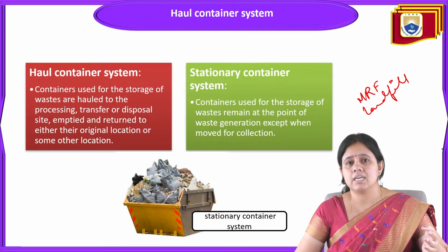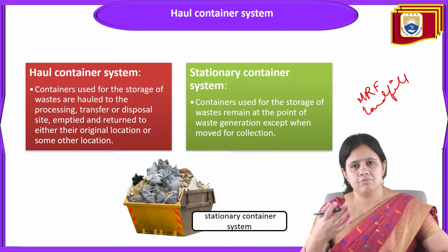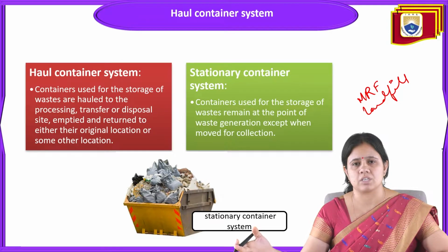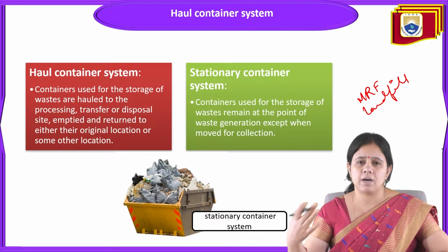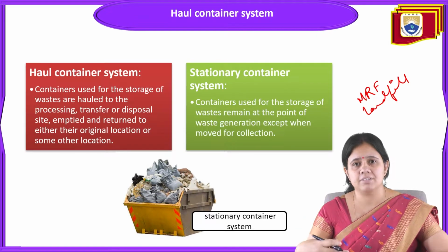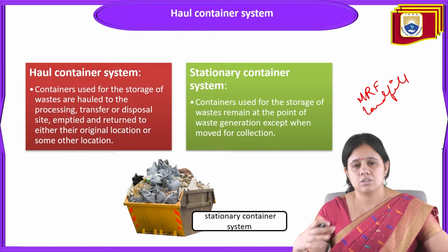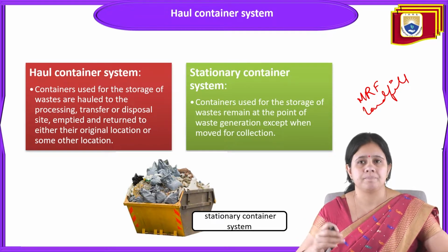But in the stationary collection system, they will collect the waste into their vehicle and then go to the next location. Like this, hauling will be done from location to location, in which the time for coming and depositing the waste at the landfill site or the material recovery facility will be reduced. So the stationary container system is better.